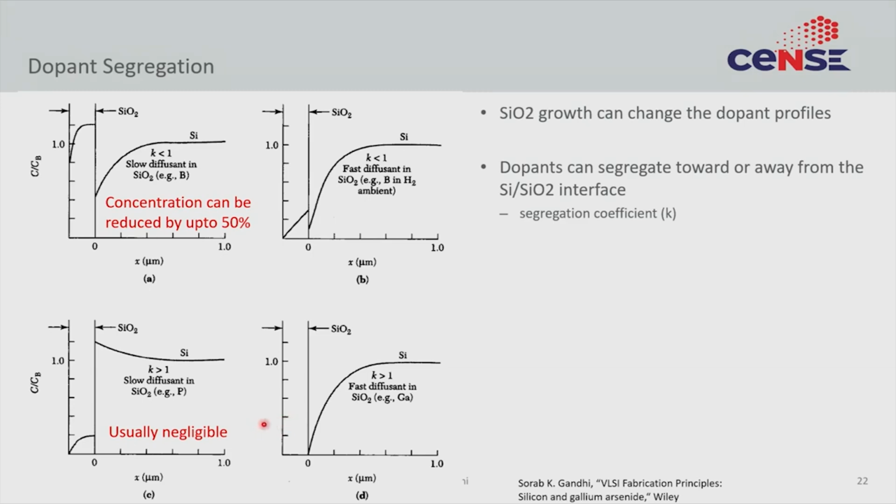So it keeps out diffusing into the gaseous medium. So the concentration in the silicon dioxide can never be maintained. So even though the distribution coefficient is more than 1, unfortunately because there is no concentration of the dopant in the silicon dioxide, it keeps pulling the dopant even from the silicon. So unlike here where you were seeing an accumulation of the dopant, you start seeing a depletion of the dopant.